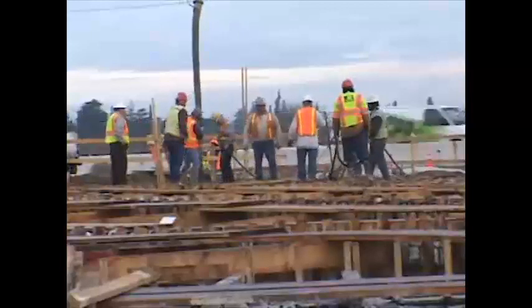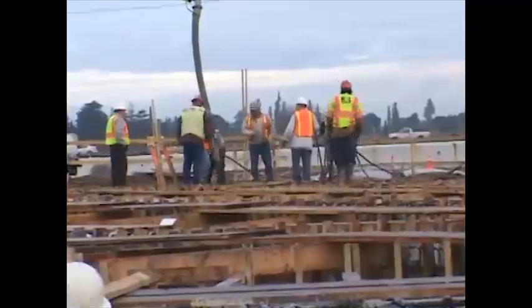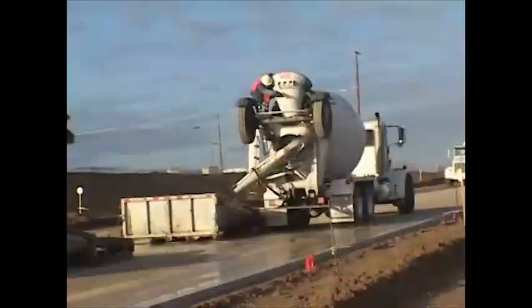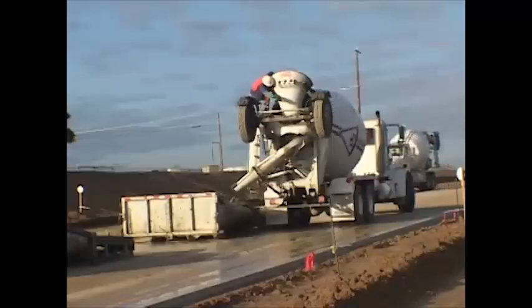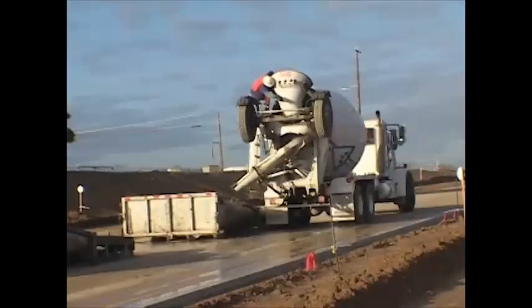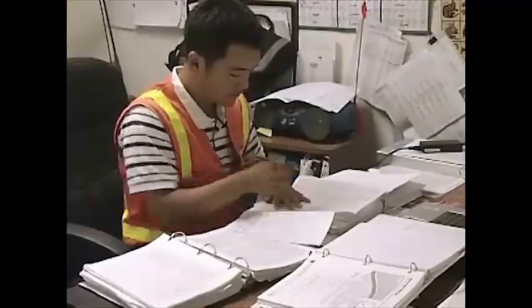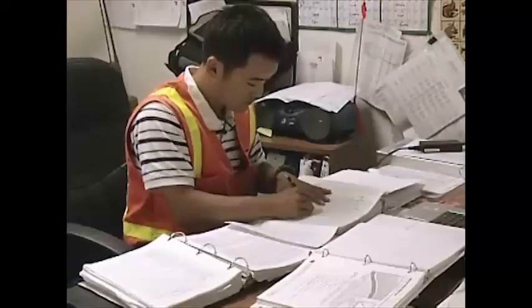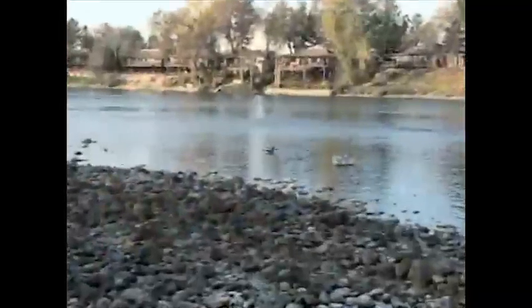Concrete slurry waste handling, on-site concrete washout facilities, transit truck washout, and the removal of temporary concrete washout facilities are typical concrete waste management activities. The contractor must conduct concrete waste management activities according to the guidelines provided in the project special provisions to minimize or eliminate the release of concrete waste materials into the storm drain system or watercourse.